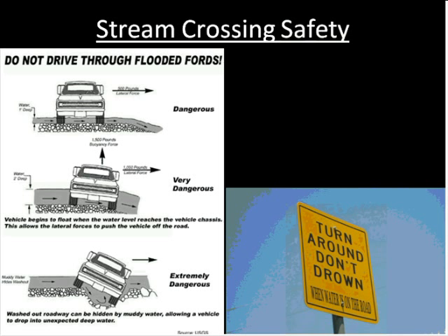All right, one final consideration I'd like to cover today is crossing safety. I think it's important to emphasize that many of the techniques I've talked about are crossings intended for use under low water conditions. Things can get dangerous as flow depth increases at a crossing. Both lateral and buoyancy forces increase with depth, and muddy water can hide any scour damage that may have occurred during high flows. So taken together, these factors create potentially life-threatening conditions at flooded fords. Consequently, we should inform landowners about the dangers of flooded fords and include signage whenever we can.